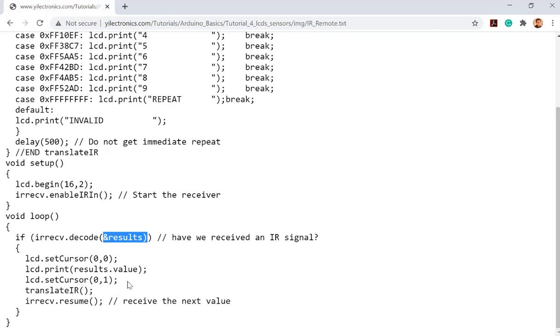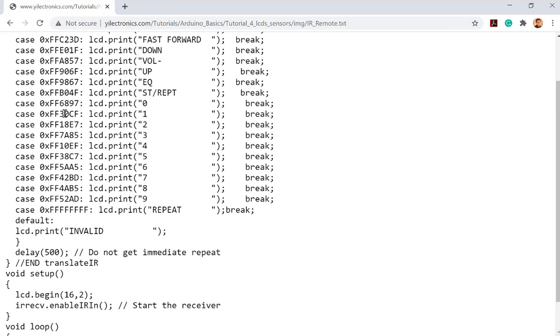You just want to print that variable to your serial monitor so you can see that value. You push it, open the serial monitor, see that value and write it down, or copy and paste it to a spreadsheet until you are done with all the push buttons. Do you understand that? You know what to do for this one? Great.